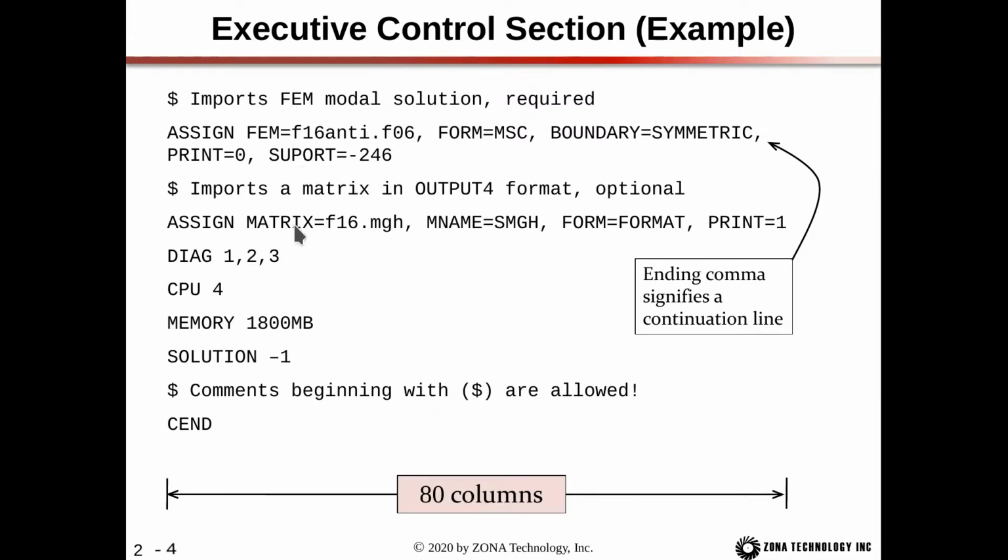The assign FEM and assign matrix can end in a comma. These are the only 2 cards that support that feature. This allows you to break up the assign FEM or the assign matrix onto 2 lines. This is useful in particular if your file name is quite long, which could be the case if your solution file is in a different directory. So if you have to go up 2 or 3 levels, you'd have ../../, and then if you go down more directories to a file, you could imagine that this string can get